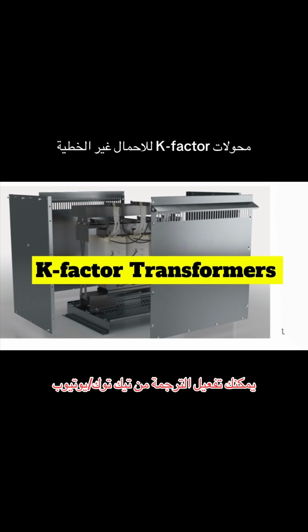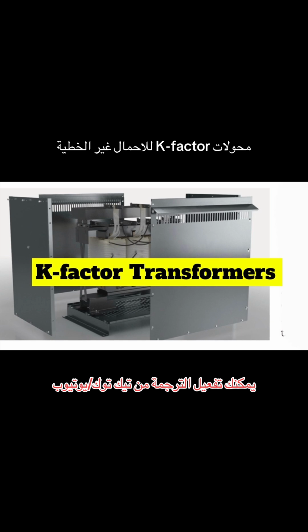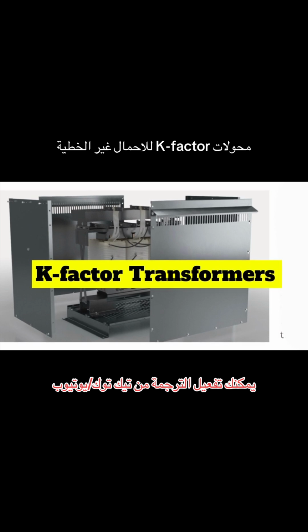Now, both the voltage and the current can have these harmonics, but the paper is really focused on the current harmonics, and it says they're the ones that cause the real issues for transformers. So think of it like our nice, smooth electrical system is experiencing these little tremors, these little hiccups. These specifically bother the transformers, huh? Why is that? That's the thing. These harmonic currents generate extra heat inside the transformer. And it's not just heat. They can cause some mechanical stress, too. It's like shaking a delicate machine.